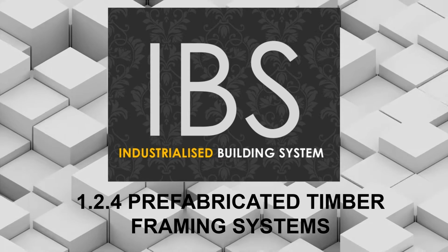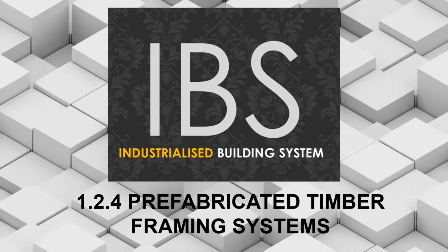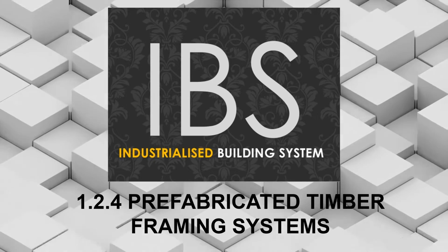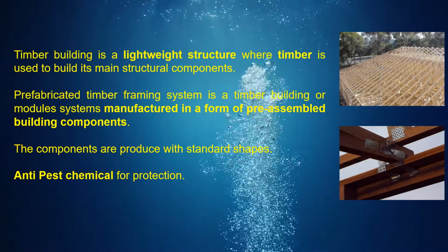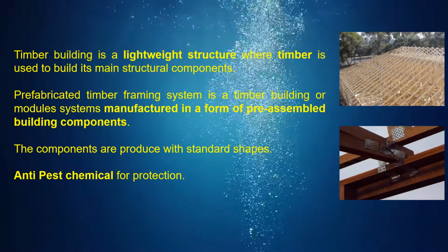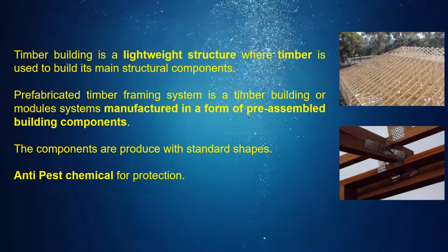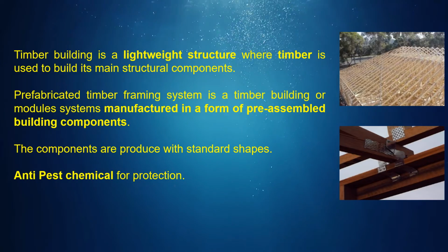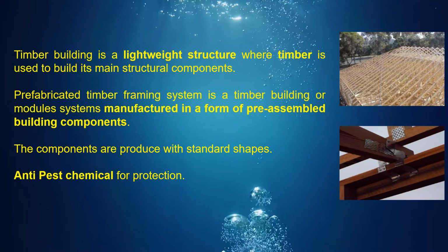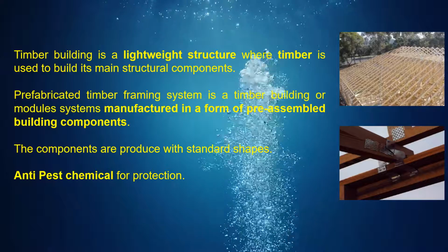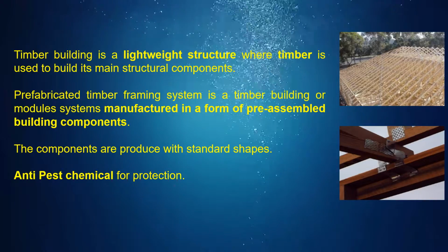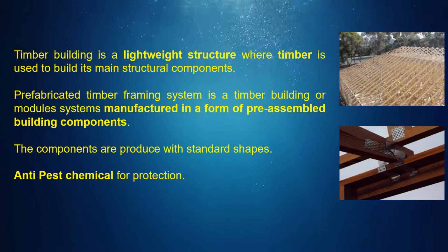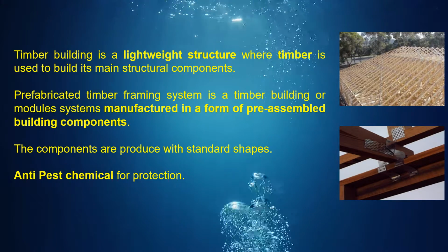Lesson for today is prefabricated timber framing system. Timber building is a lightweight structure where timber is used to build its main structural components such as columns, beams, floor, wall, roof, and trusses by using various types of joinery techniques.